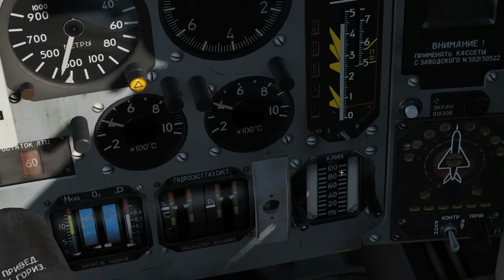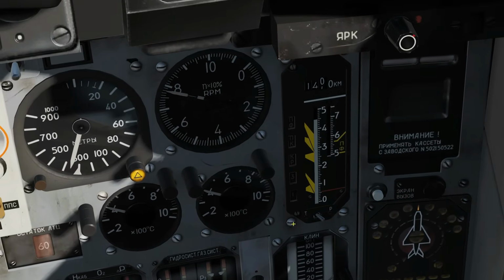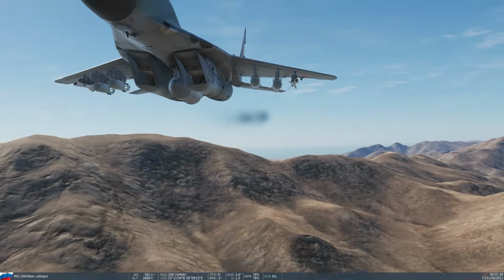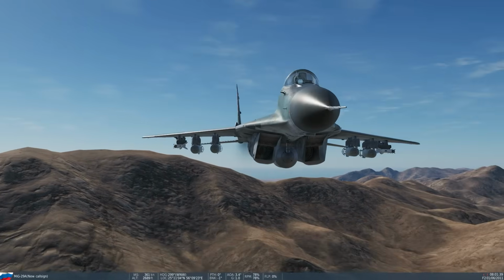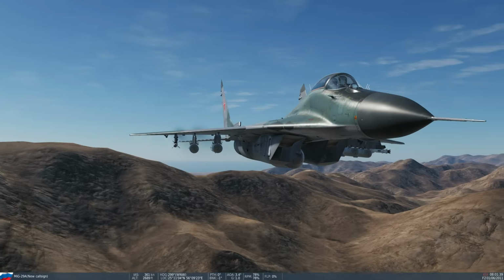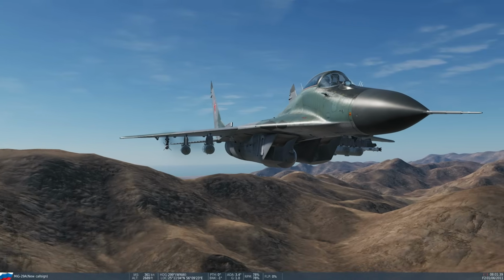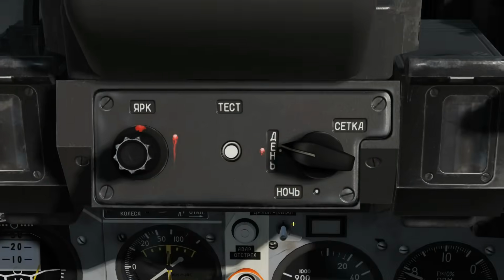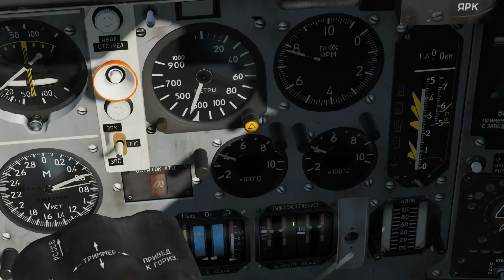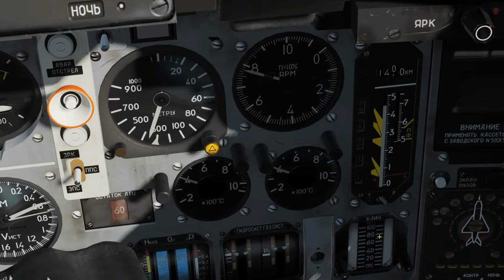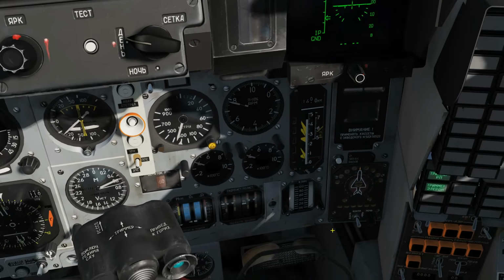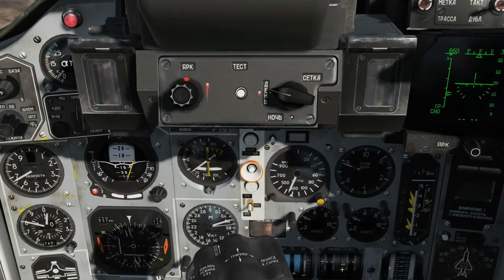This gauge here shows the intake ramps. There are intake ramps inside our intakes. You can't really see them, you'll have to take my word for it. I think they drop down from the top down to the bottom. They precondition the air for supersonic flight. It's a typical thing that breaks down on a fast jet. And here is the indicator in percent of the ramp position. Going kind of a funny direction here. Maybe I should skip back a bit.